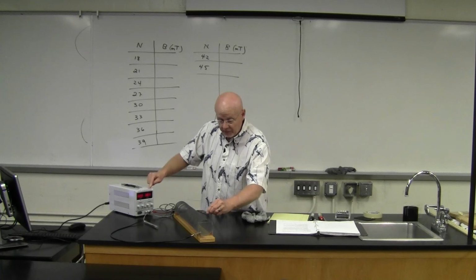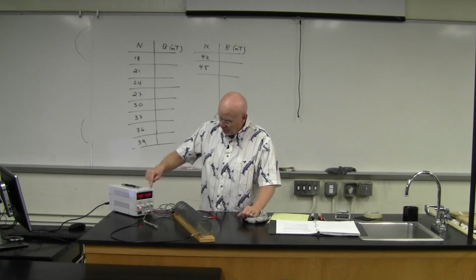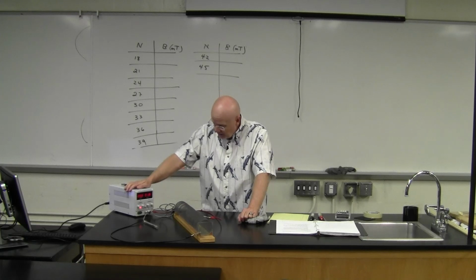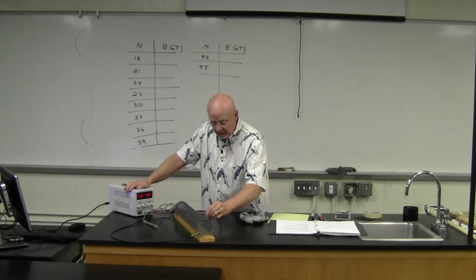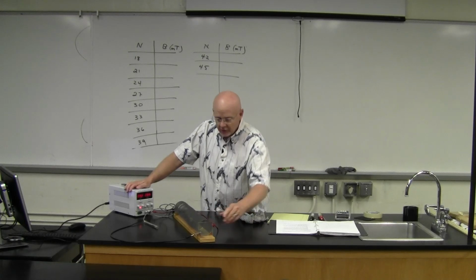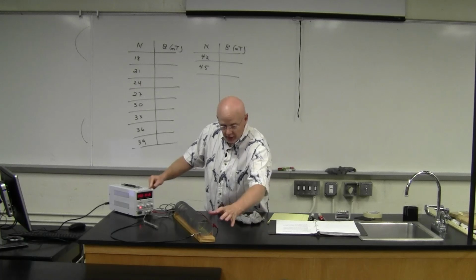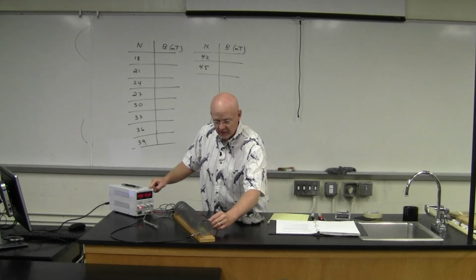And so the computer on here adjusts the voltage accordingly so that I get the 2.5 amps. So that's a nice little design of these power supplies. We can set them for a constant current source. And so see, 2.5, even though I'm going a shorter distance and less resistance. So that will become useful.